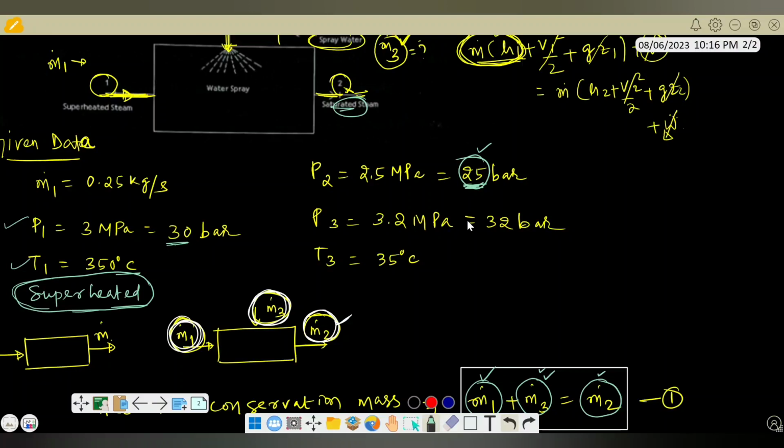And what is given? We are given this pressure value, that is 25 bar. So, saturated property and pressure, that is 25 bar. Okay, let us move. This is the temperature table, right? If temperature were given, then we would be using this particular table. But we are given the pressure value, so we'll be moving to the pressure table.